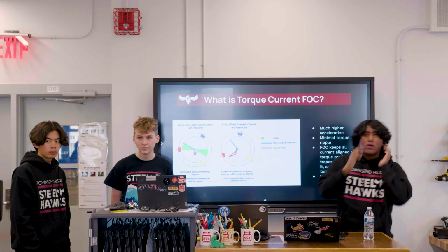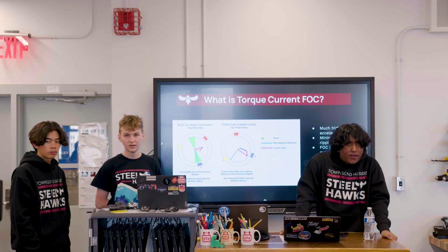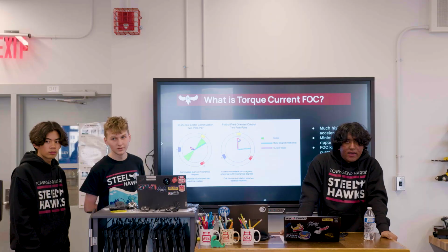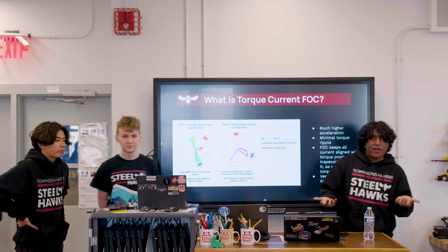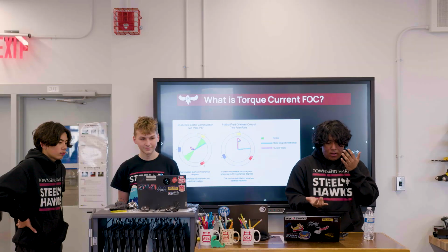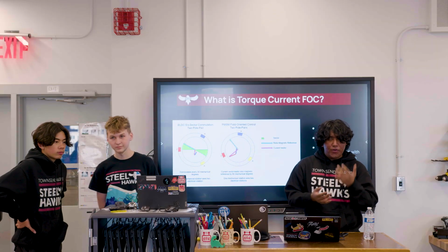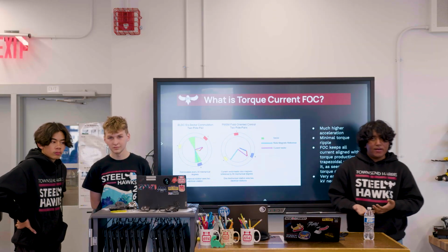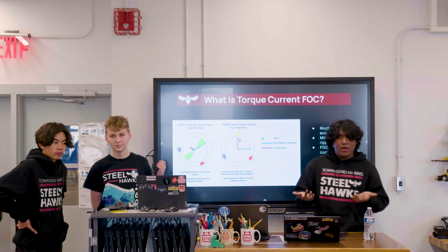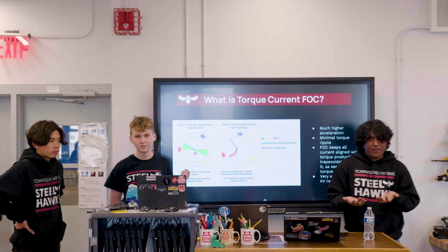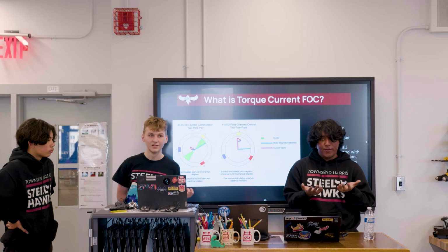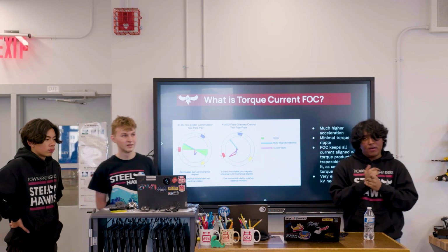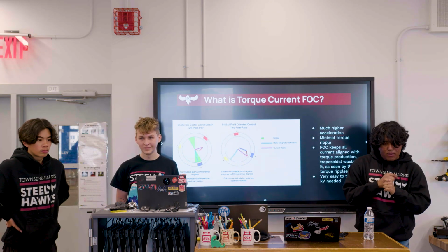Yeah. So with libraries, it's just Phoenix 6. You know when you need Phoenix 6 to run a motor anyways, right? Yeah. Are you familiar with motion magic and how you run PID on a motor? Yeah, so literally all you do is, instead of using, for now I'm going to say position voltage, that's a normal PID controller.